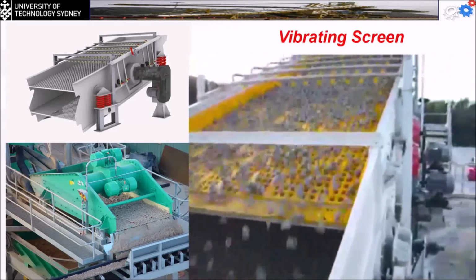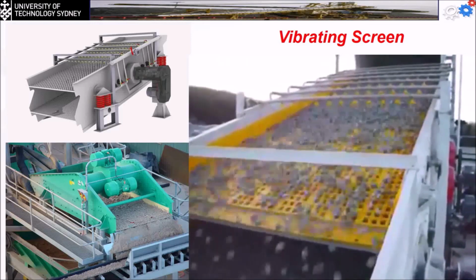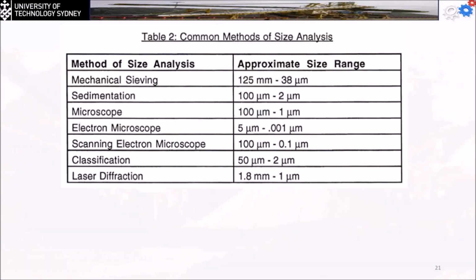Okay, so these are the common methods of size analysis, depending on the size of the particle itself. If the approximate size range is between 125 millimeters and 38 micrometers, simply I can use the mechanical sieving process. The sedimentation process is for smaller sizes, between 100 micrometers and 2 micrometers.